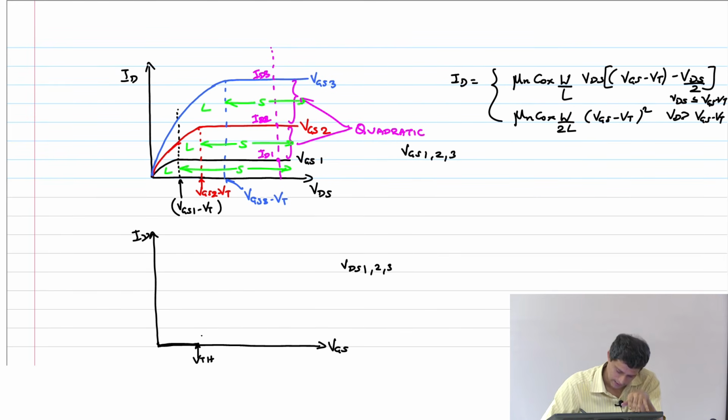right? And then as soon as my VGS exceeds the threshold voltage, if VDS is now fixed, in what region of operation will the transistor start? How does it matter? Let's say I have taken VDS to be some 100 millivolt, some small value.